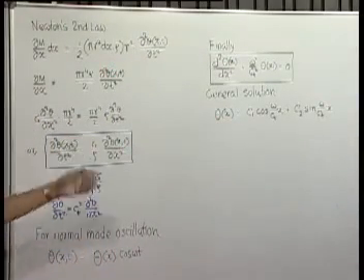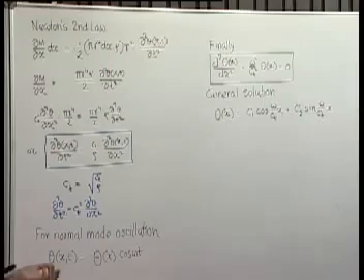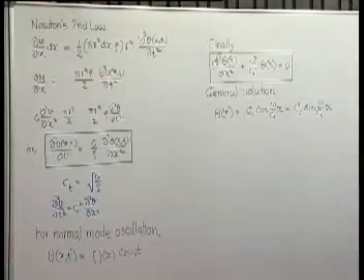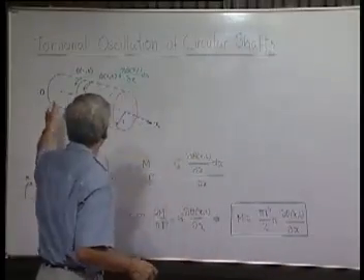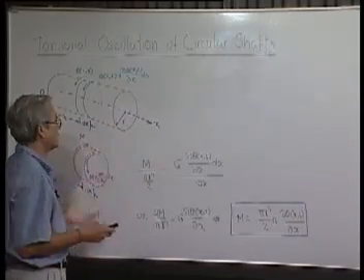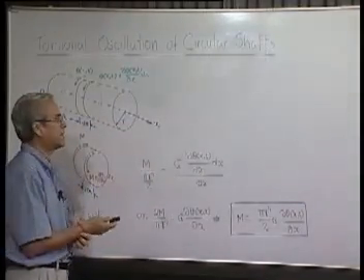Omega can be found out from the boundary conditions of the shaft which is given. So the solutions will be very similar. That means both ends free, one end free one end fixed, or both ends fixed. We will get similar kinds of things.